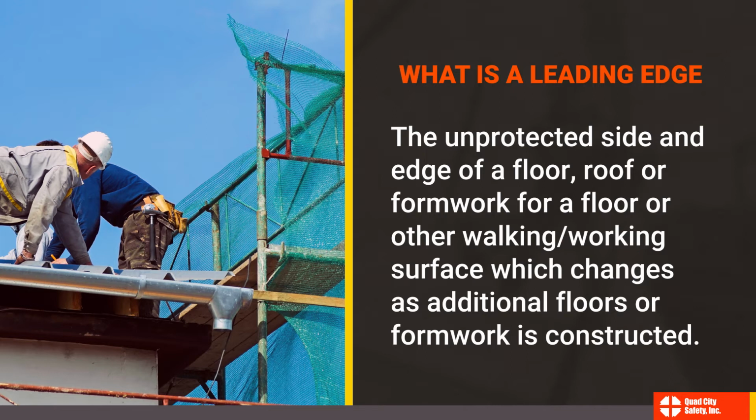The best way to explain why this is important when choosing a self-retracting lifeline is to imagine a construction worker installing steel on a new building. He steps away from the anchor point and has the potential to fall over the edge of the building. Because most of the time they're anchored at foot level, they have the chance of falling further than typical applications that are anchored at or above shoulder level.